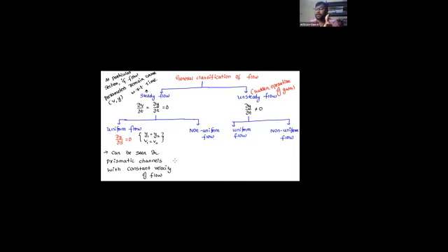And if velocity is going to be constant, from the continuity principle, if velocity is the same, then flow area is also the same. Then depths are also going to be the same. Literally, I can say shape constant, slope constant, size constant, and depth is also going to be constant. Is there any degree of freedom here? No. That is the reason why uniform flow is an ideal flow. Uniform flow does not exist, but we do assume the uniform flow as an ideal flow.